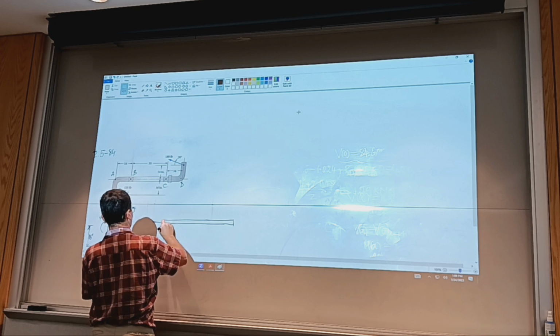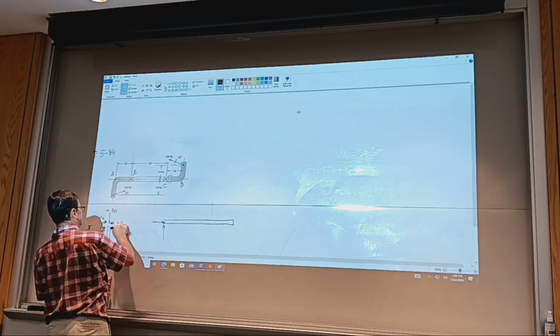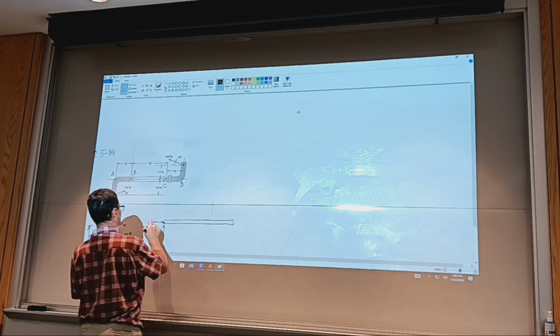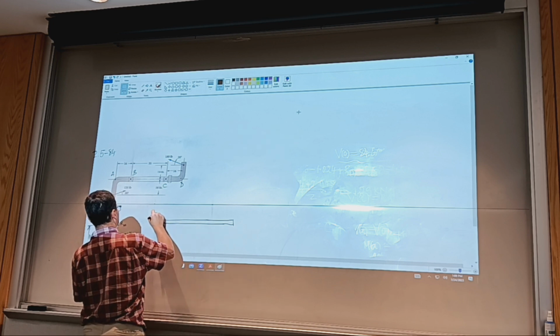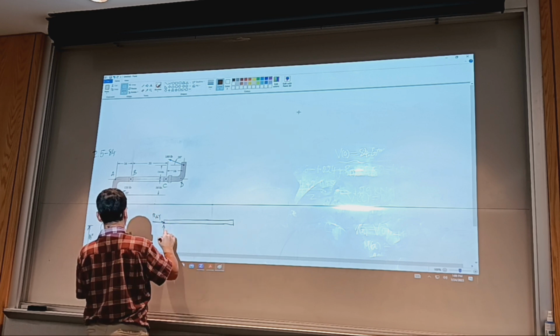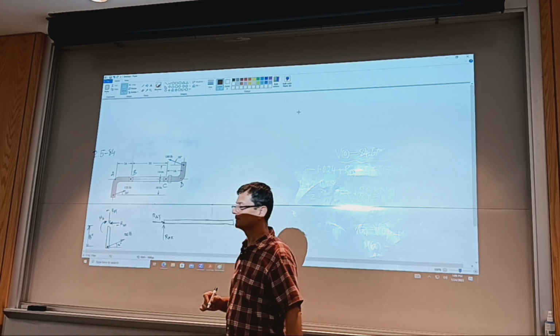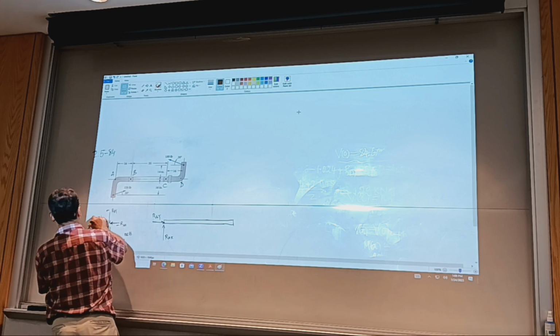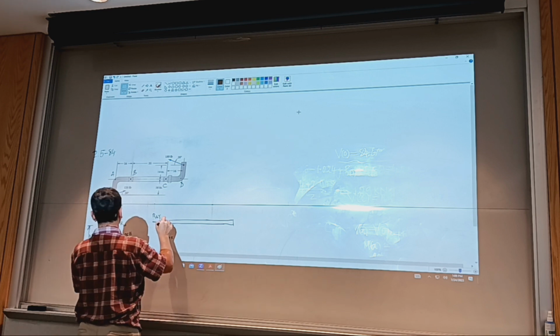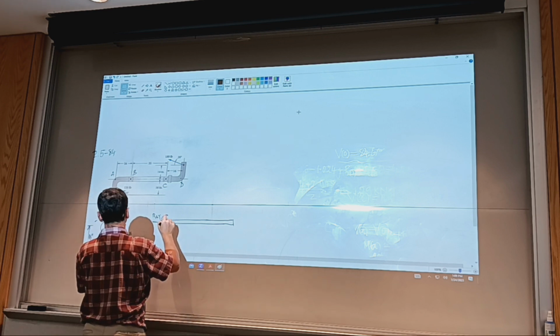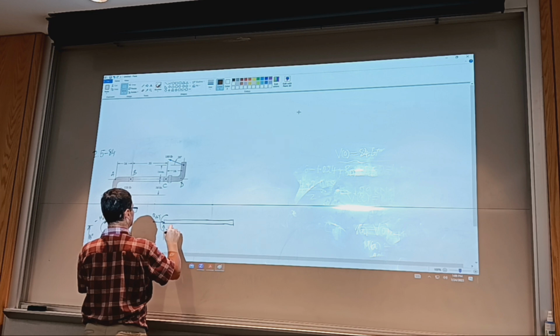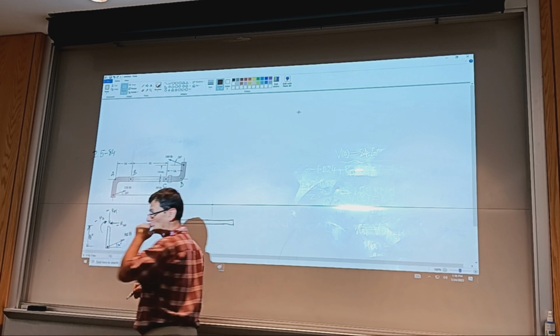So if I put a minus here, because this will be the main one that we'll be analyzing, I can call this R_AY with a plus, R_AX with a plus. Does it make sense? And then the moment, M_A, put a negative and represent it here as a moment that is in the opposite direction, M_A. Does it make sense what I did?